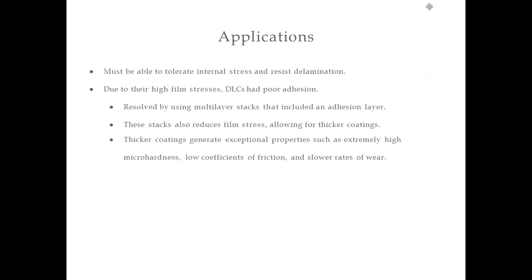So the material that we deposit on must be able to tolerate internal stress and resist delamination. Due to high film stresses, a lot of times these diamond-like carbons have poor adhesion to the parent material.